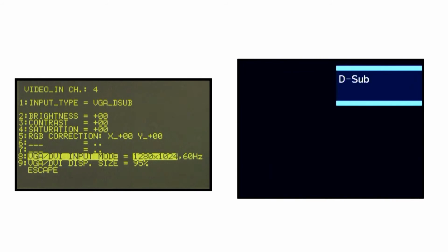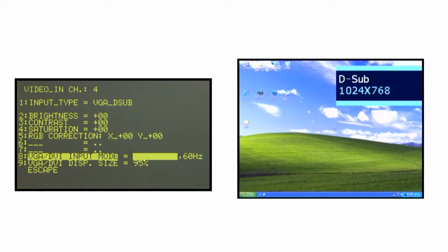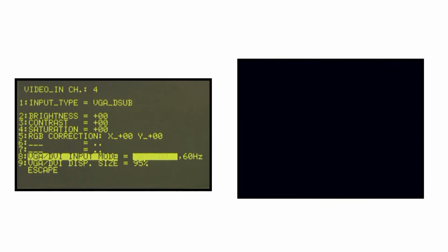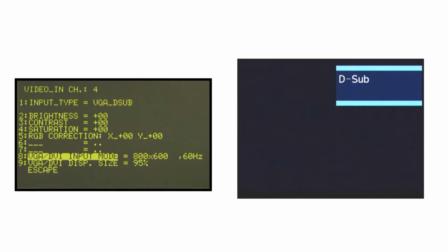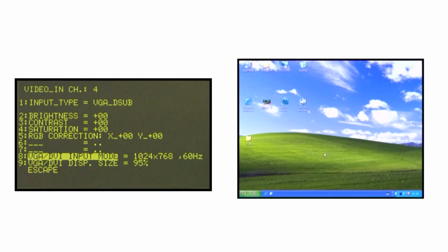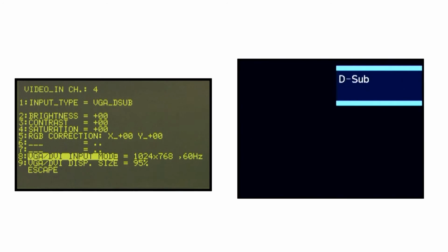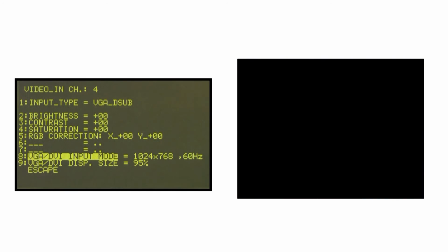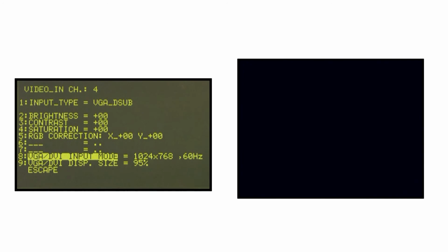The configuration and the resolution of the computer signal have to be aligned in order to get the best output effects. If the output shows a flashing black display, it is likely due to an incorrect resolution selected. Change the computer signal output resolution or change the SE900 input mode to fix this.